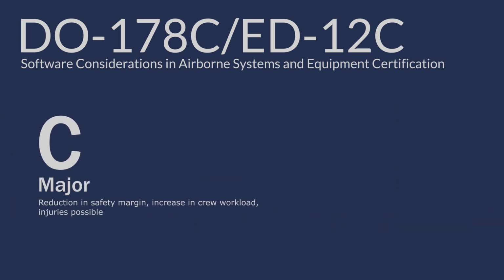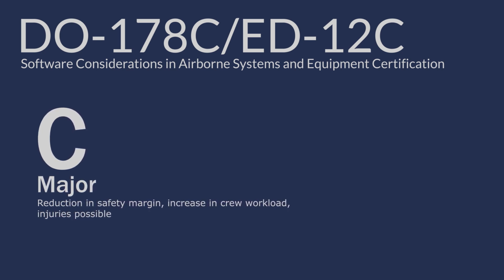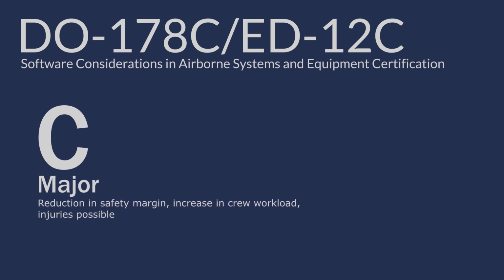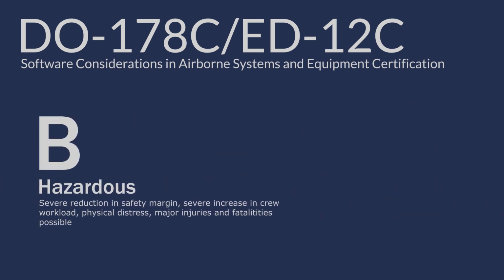Level C is a major failure condition. Failure of a Level C system would significantly reduce the safety margin or significantly increase the crew's workload. Passenger injuries become possible with a failure of a Level C system. An example of a Level C system could be an electronic flight bag that contains copies of operating manuals and navigational charts. Level B failures are considered hazardous.